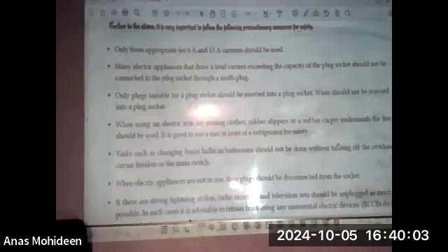And when ironing and such, it is better to wear rubber slippers or put rubber carpets beneath the feet, so that no current passes even if there is a leak. But if you know there is a leakage and you still stand on the rubber carpet, putting your life on it, it won't work. If you know there is a leakage in that gadget, you have to repair it, because the same current leaking out continuously will cause burning as it heats up.